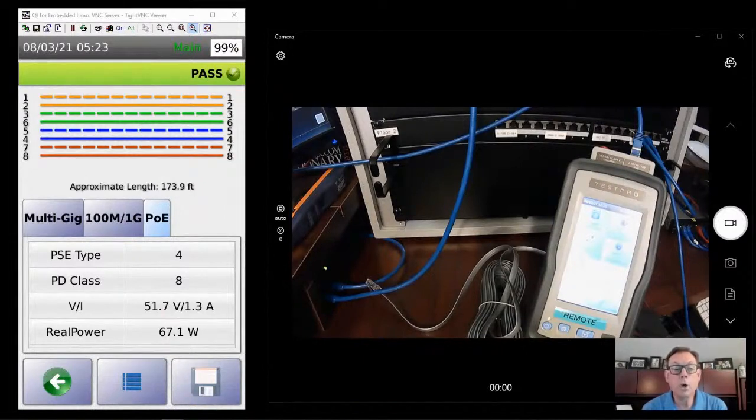If we're referring to what could cause that resistance unbalance, it could be the quality of the cable. It could be termination practices, which would also typically lead to other components of the overall Cat6a test failing. So, for instance, if at the point of termination, for whatever reason, you had an extra couple inches on pair 1 versus pair 2 versus pair 3 versus pair 4, and you made each of these a different length before you terminated them, that would be a little bizarre, but it would cause some differences in resistance.